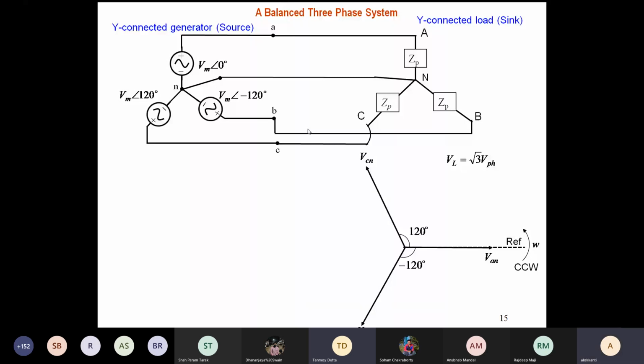Suppose you consider Eden Gardens. Whenever there is a match, it will be lit up. The supply is three-phase power. If the whole stadium is divided into 3 blocks, one block will be connected through the R phase, one through the Y phase, and the other through the B phase, assuming each block consumes the same amount of electricity. That is how the power companies try to balance.